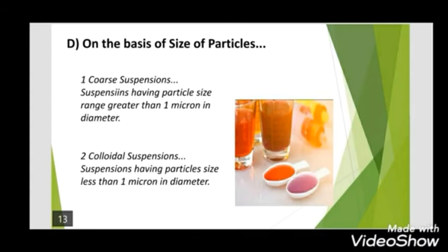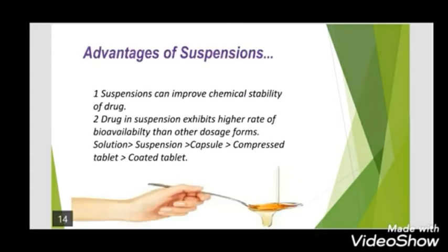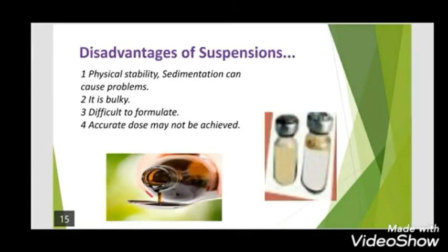Next we see the flocculating agents. These flocculating agents promote flocculation by causing the colloids and other suspended particles in the liquid to aggregate, forming flocs. Examples of flocculating agents are multivalent cations such as aluminium, iron, calcium and magnesium. Next are deflocculating agents. These deflocculating agents prevent flocculation by reducing the viscosity and are called dispersants.